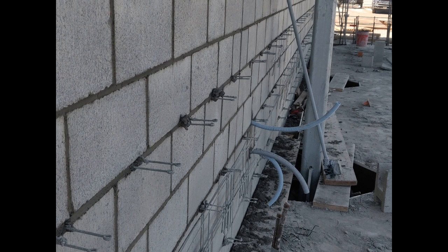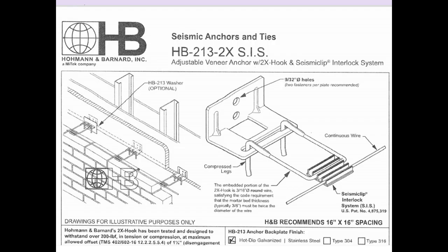Provide joint reinforcement with factory-formed corners and intersections. If approved for use, joint reinforcement may be furnished with adjustable wall tie features. Submit one piece of each type used, including corner and wall intersection pieces, showing at least 2 cross wires.